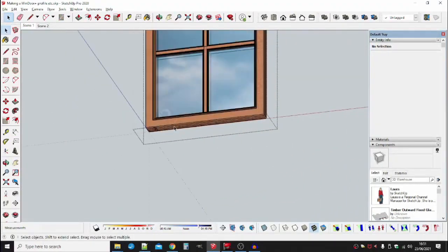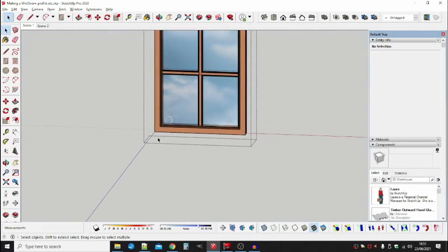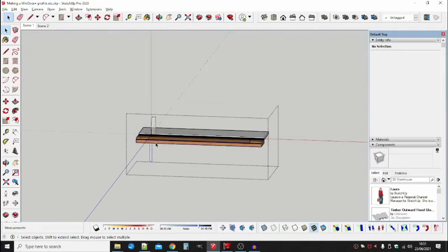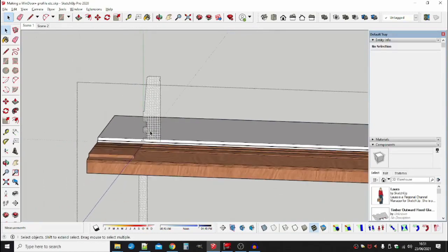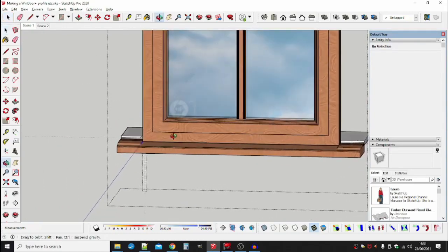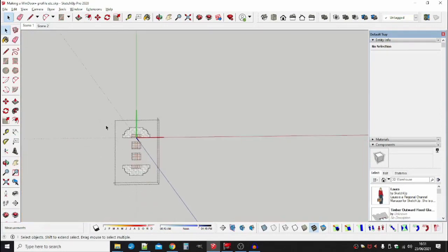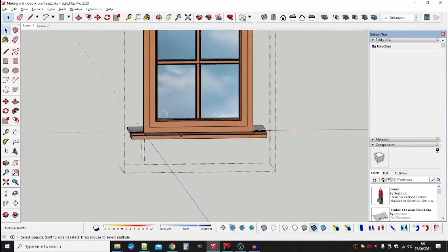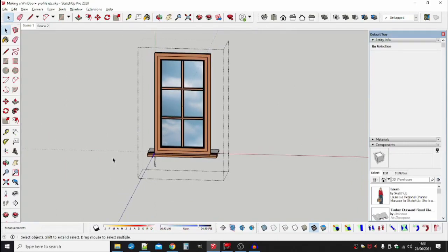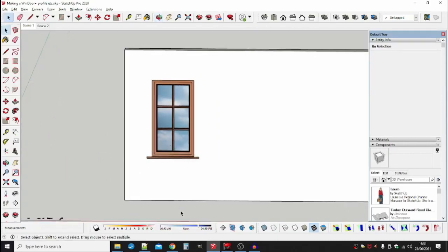You can check the profile components by turning on Hidden Objects in SketchUp's View menu and clicking into a sash, outer frame or sill. You will find the hidden sash and glazing bar profiles at the bottom left hand corner of the sash, and the hidden outer frame profile at the bottom left hand corner of the outer frame, ghosted. The sill profile will be at the left hand end of the sill, again ghosted.